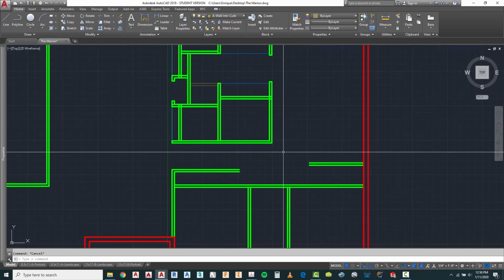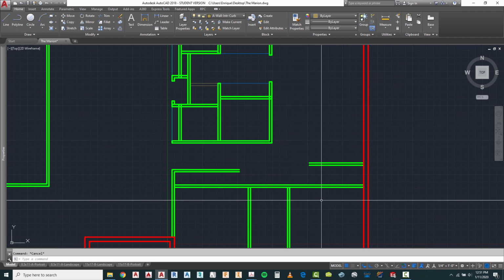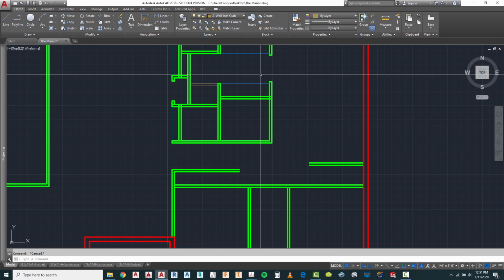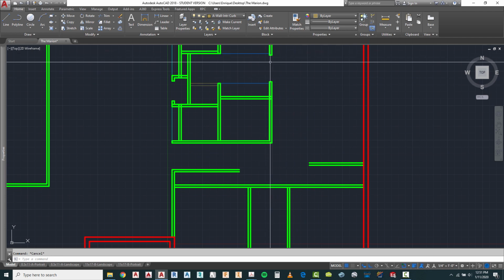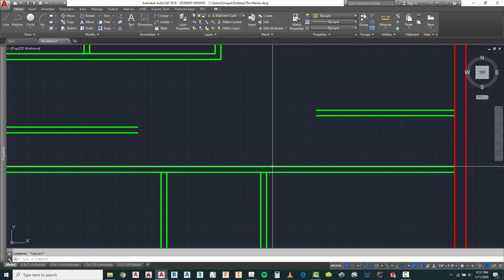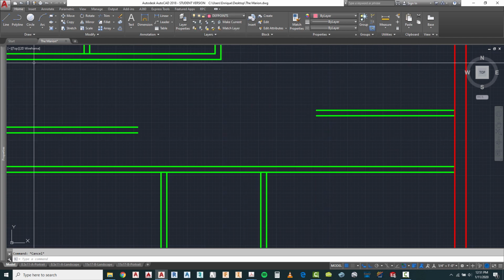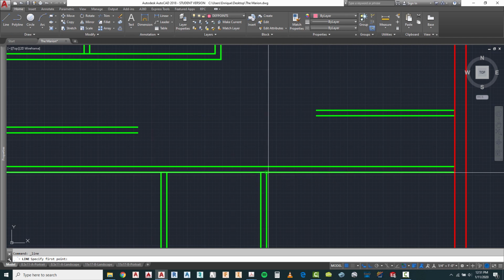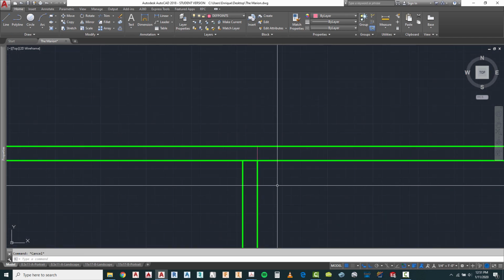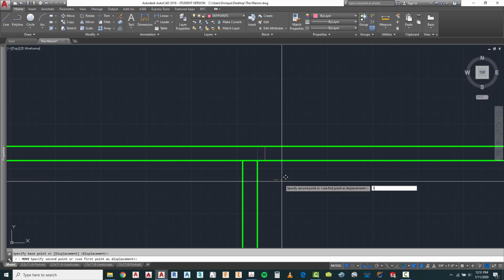Well, at what angle is this wall that closes off this set to? Now remember, we had to worry about our 3 inches on each side of the door. We're going to have that same condition here. We're going to want 3 inches, the typical door that goes into a bedroom, then 3 inches before we can lay out this wall. So I'm going to go back to my depth point layer. I'm going to draw a line in here. I'm going to move it or offset it 3 inches this way.